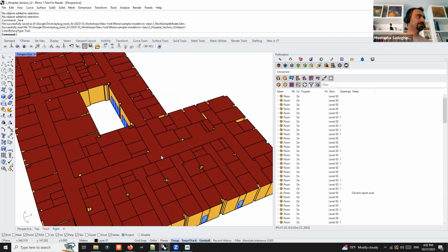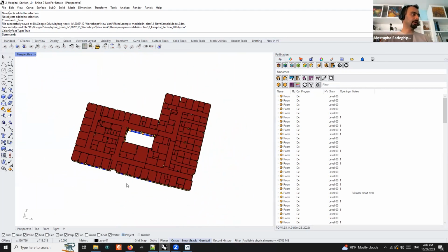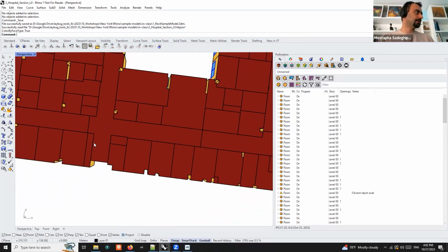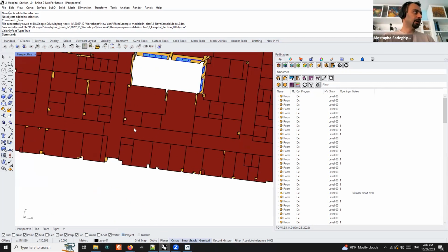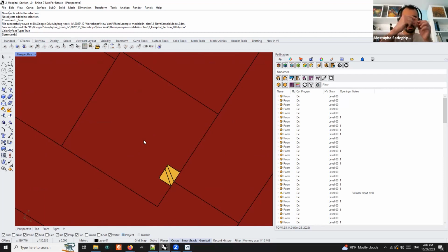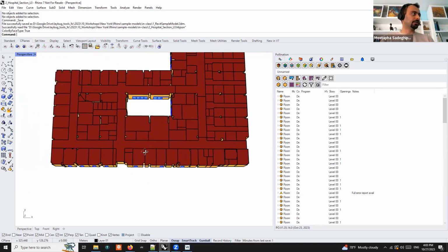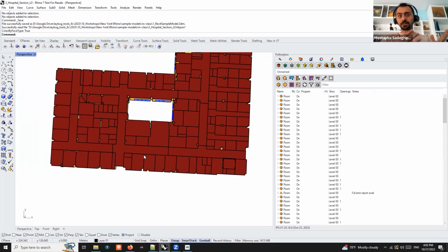So this is a real world scenario, right? That was the Revit sample model. We tried to make things fail for you. This is what you really get if you export something from Revit. And in this case, they didn't spend the time, for example, to make the columns not room bounding. Around every column there was a small interior wall, so it wouldn't see the column in any case, and you end up with this. And now I'm going to show you how to fix this if you are up for it.